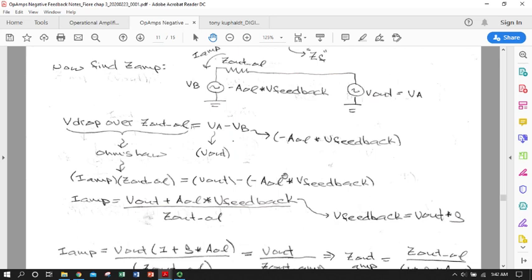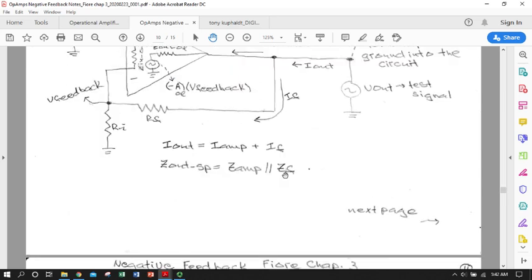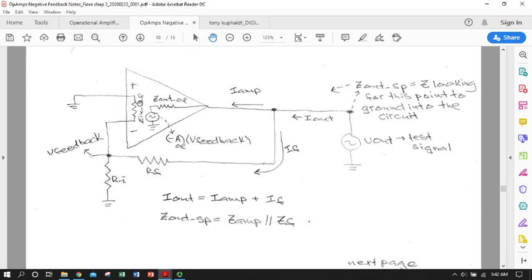So we're just doing a lot of substituting in of quantities we've already derived and that we've denoted on our test circuit schematic. So we're relying really heavily on this representational model of the op amp. And we had said back in Chapter 1 that we would use a lot of very simple models of resistor networks and current and voltage sources to represent these very, very complicated circuits that actually make up the insides of the op-amp. So that's what we're doing here.